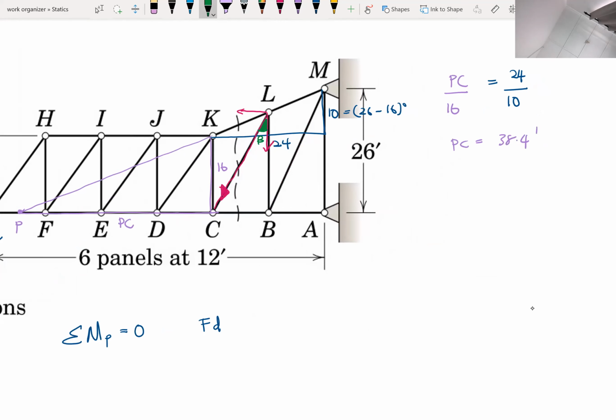Again we have to know. Let's say we just use the concept of tangent. We know this one, which is 12, and then we know this one, which is the distance, 16 plus 5, which is 21. So tangent beta is 12 over 21. So beta we will get 29.7 degree.